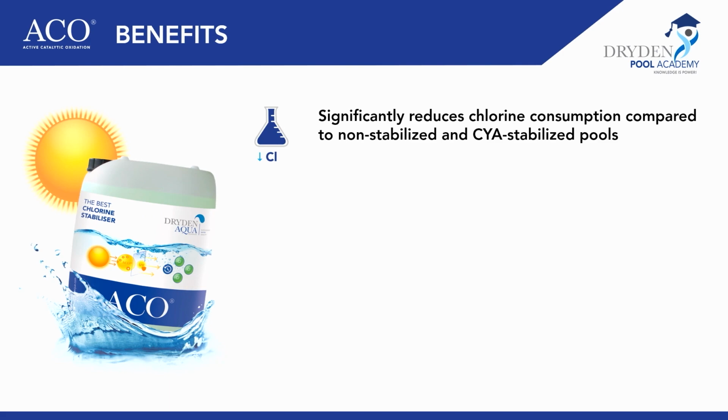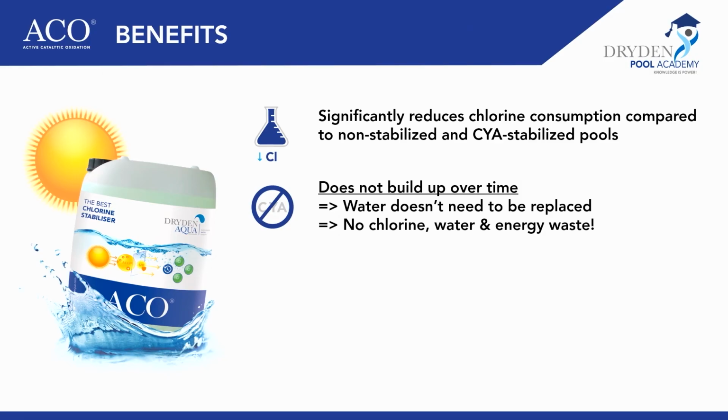The benefits of ACO. With ACO, you will significantly reduce chlorine consumption compared to non-stabilized swimming pools, but also stabilized swimming pools with cyanuric acid. Next up, it does not build up over time. As we mentioned, the ACO does not bond with the free chlorine, so the water does not need to be replaced. So no chlorine, water, and energy wastage.